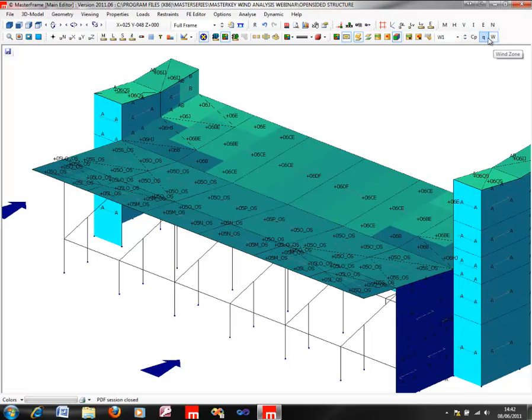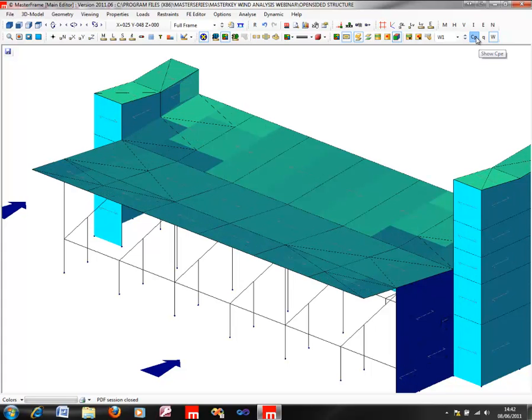In fact, if we look at the zoning designation, where we detect something as an open-sided canopy, we put an underscore OS, open-sided, against that in the zoning designation. If you don't see that, then you know the program has assumed it to be a standard canopy, whereas in this case it said no, you're actually too large a projection, you're an open-sided structure. So that's useful, to be able to actually see that classification taking place.